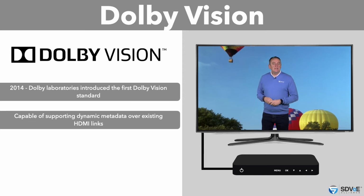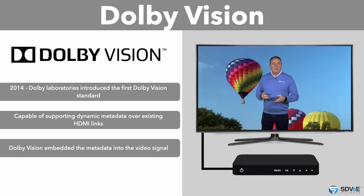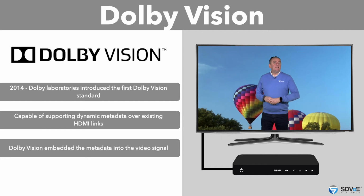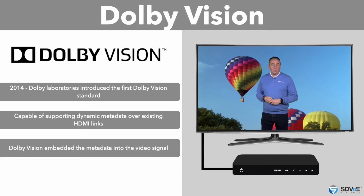Dolby Vision did not require a new HDMI standard, as it was embedding the metadata into the video signal. Knowing that current versions of HDMI would not pass the Dolby Vision dynamic metadata, Dolby developed a way to carry this dynamic metadata across HDMI interfaces as far back as version 1.4b.